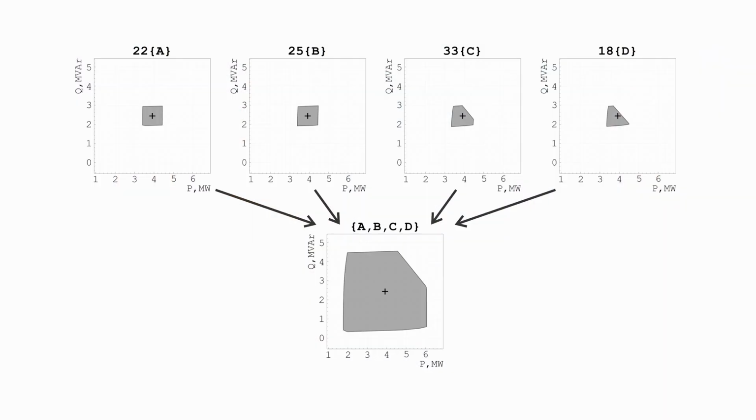Then, if we activate all units together, we can estimate the absolute limits of aggregated flexibility, and we can produce a picture like this. So again, we see that this network is quite flexible. We can deviate from the initial operating point, we can increase power consumption or decrease it, and this is what most of the papers do when they analyze the aggregated network flexibility, where they estimate nodal operating envelopes. We discussed in the previous video how we can do this using iterative optimal power flow models, where we can approximate the boundary by solving a point-by-point OPF problem. So for this case, we did the same. We found the boundary of the aggregated flexibility area.